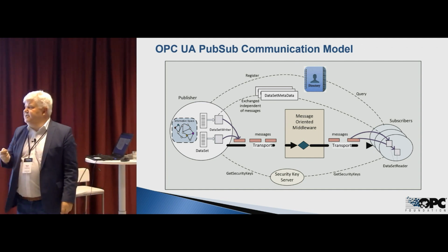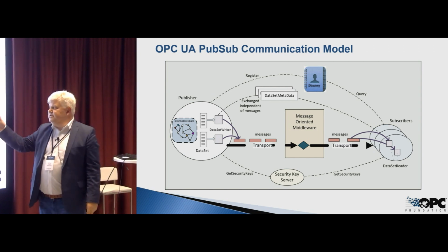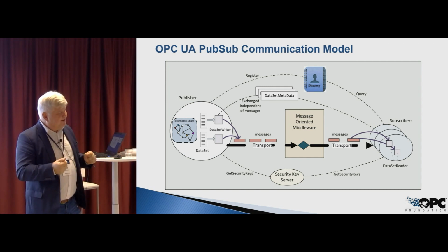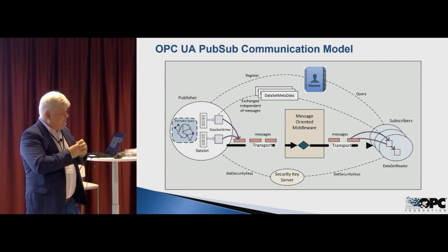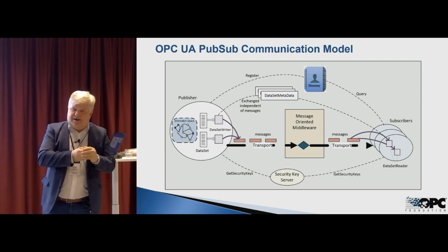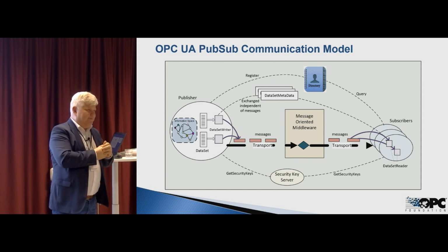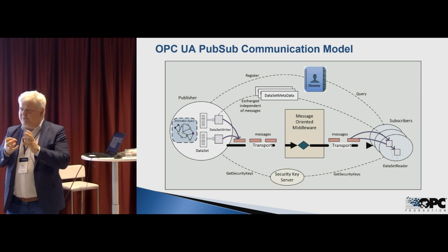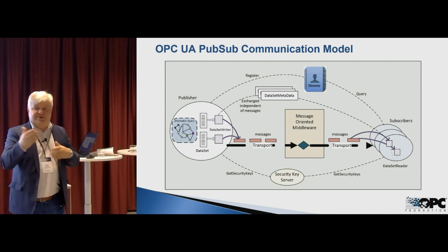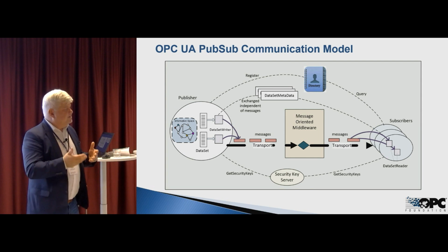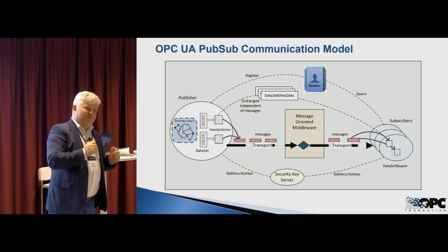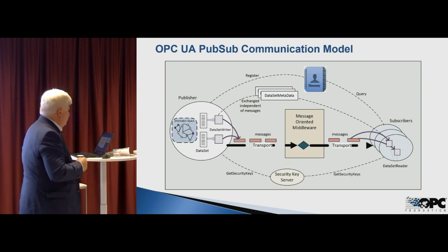So this stream of data and event messages is the main feature. But at the end of the day, you also need information about what the content is. Especially if we highly optimize the content, like in the binary format, think about a motion control application, the engineers fight for every bit in the message. I would not even say byte. In the working group, when we did this highly optimized binary representation, we really fought for bits in the headers. If you have these highly compressed versions, you really need that metadata to understand what the fields are, what the data types are, but also additional information, like if you have measurements, what the unit is. In the energy area, whether it's kilowatt, megawatt or gigawatt is a slight difference. So the unit matters, and that's all part of the metadata.